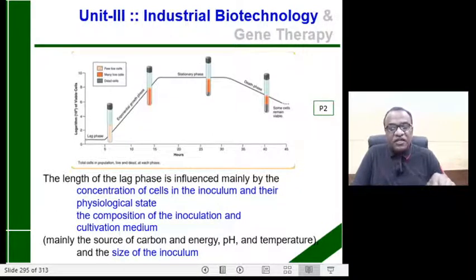Most industrial fermenters are operated in batch mode due to the relative simplicity of the process. So for efficient batch operation, it is important to minimize all non-productive or non-efficient steps so that you can achieve a higher rate of product synthesis, optimize productivity, and maximize the yield of the end product.